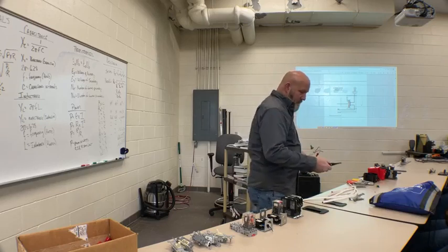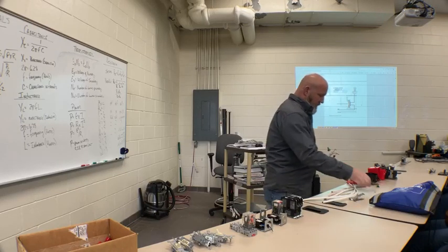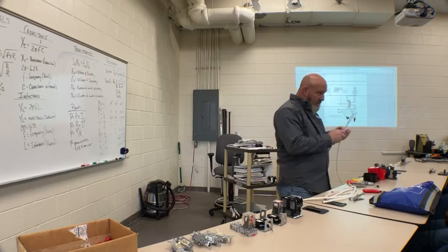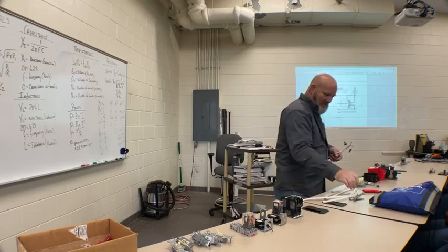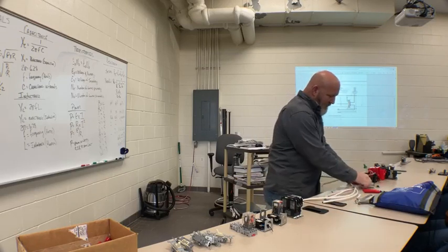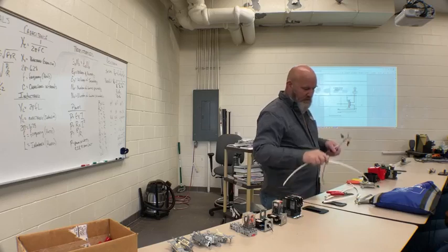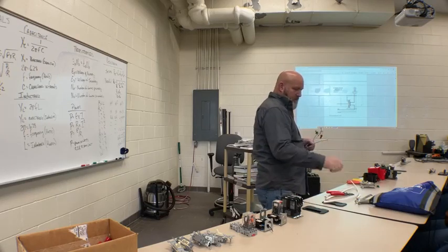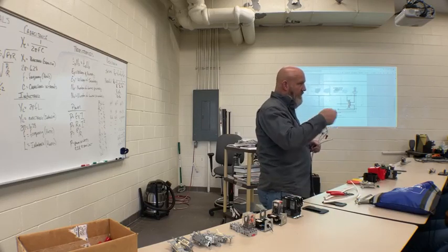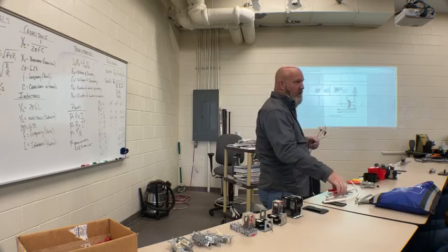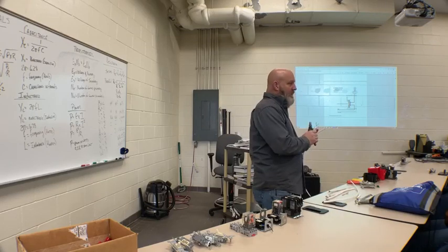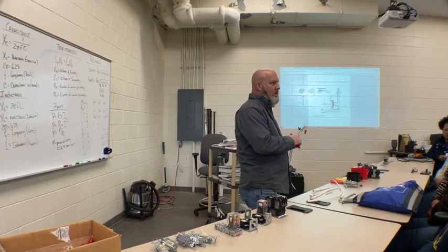So what I want to do, without anybody getting hurt today, don't stick your finger in here, is I'm gonna go cut some pieces. I would like for y'all to strip the Romex and then strip the ends and curl them. Because that's the hardest part about putting any device in, is the wire sticking out of the box, getting the wire stripped.